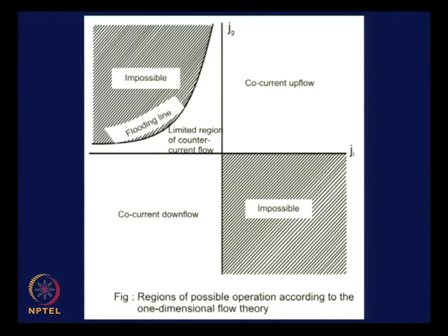Definitely we had expressed alpha, rho, T, p and local velocities in terms of the drift flux model. We found in all the cases the expressions that we obtained were a function of J21 non-dimensionalized or normalized with the individual volumetric fluxes. For all the terms we had J21 by J2 or J21 by J, something of that sort.